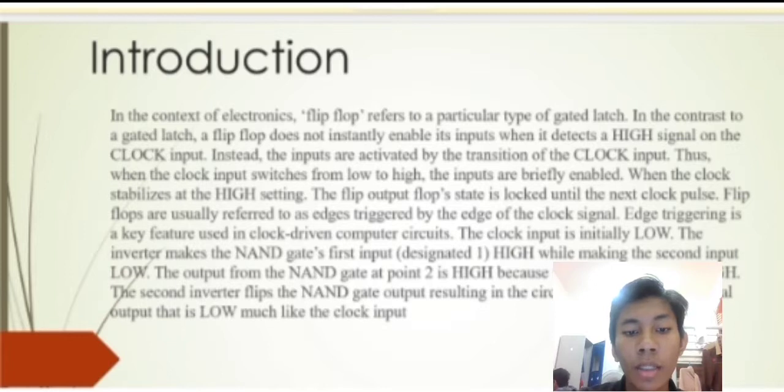When the clock stabilizes at the high setting, the flip-flop output state is locked until the next clock pulse. Flip-flops are usually referred to as edge triggered, by the edge of the clock signal. Edge triggering is a key feature used in clock-driven computer circuits.